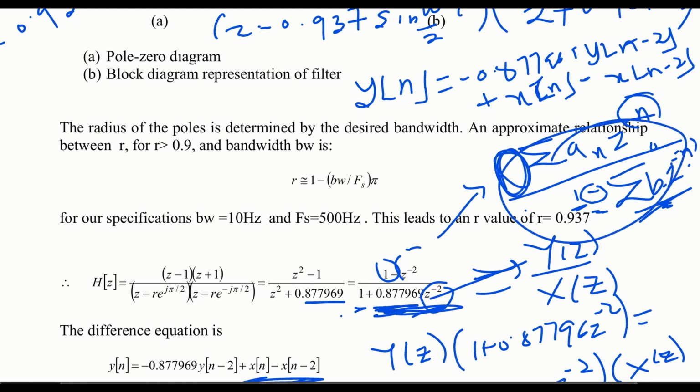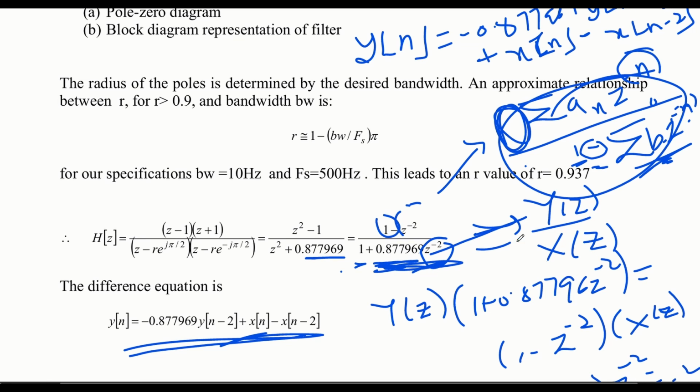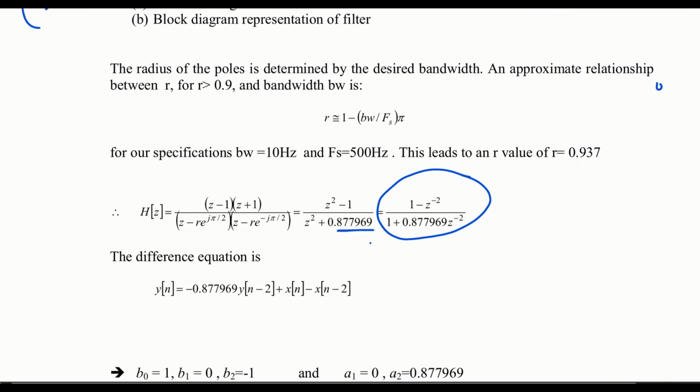But in case you still are confused about the conversion, you can go by the old route of writing it as a transfer function and multiplying it, and that one is done this way. Now in the transformation of this to the difference equation, remember that all along what we are doing is finding the transfer function of the filter.